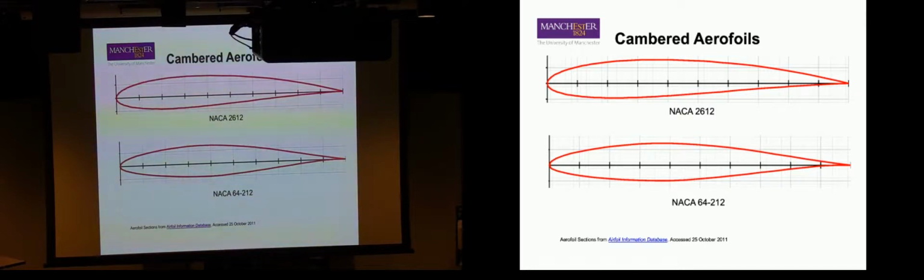Because you have to counter it in that airfoil. If it's naturally cambered, you have to then counter it with, say, a flap at the wingtip, especially swept wings, things like that. Also means that the further forward your CG is, the worse it gets. So that creates this strange feedback loop that we don't want. Okay.